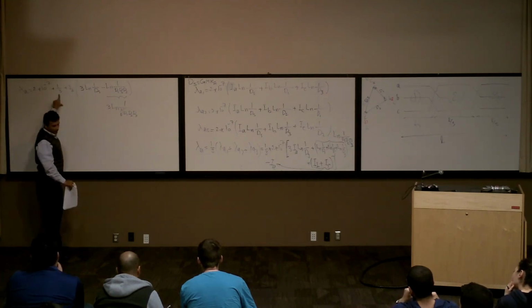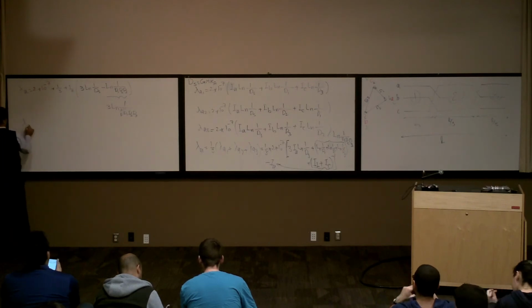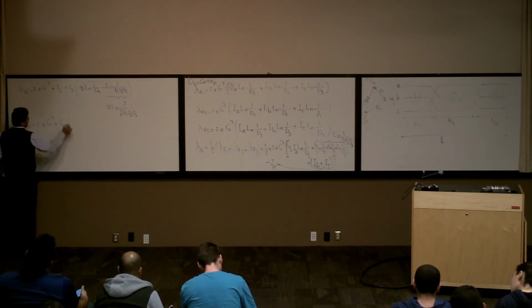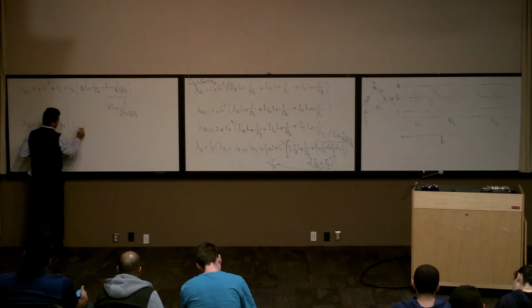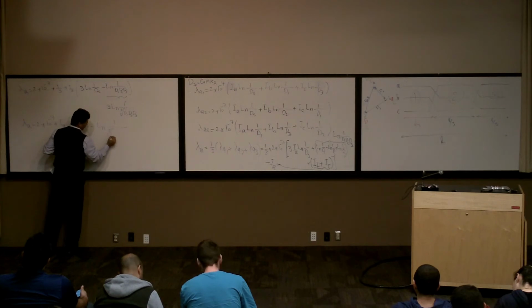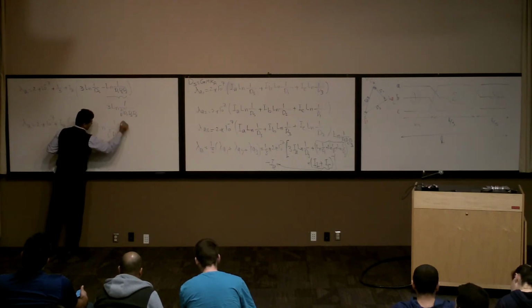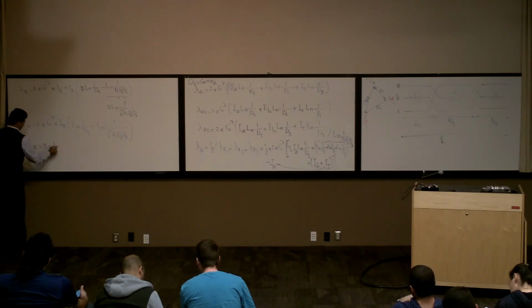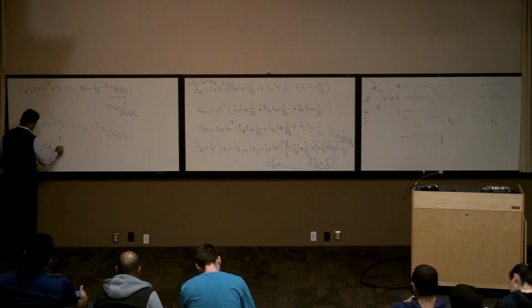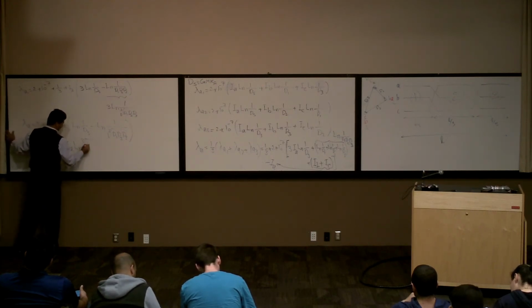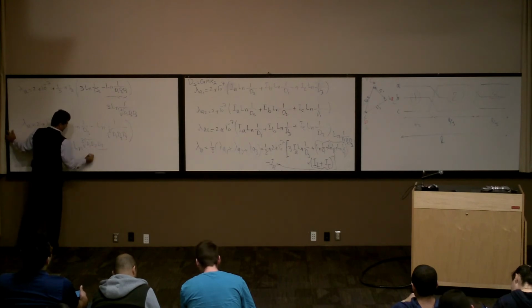You're going to cancel with this one, right? So basically lambda A is going to be 2 times 10 to the power of minus 7 times IA. Here I'm going to have only ln 1 over ds minus ln 1 over root 3 d1, d2, d3. Right? So how much is this one? Lambda A is going to be 2 times 10 to the power of minus 7 times IA ln of d1, d2, d3 over this.